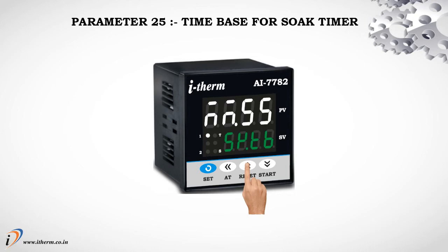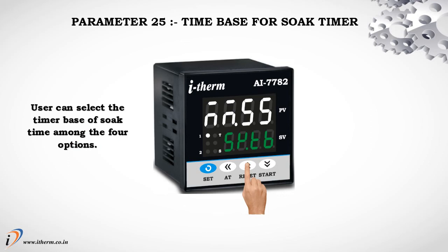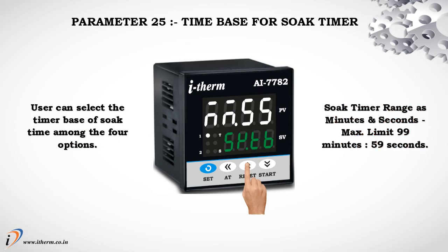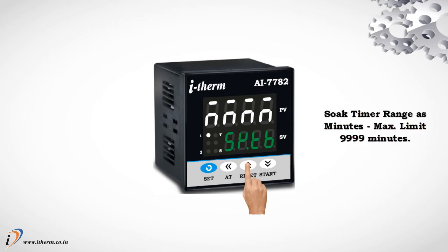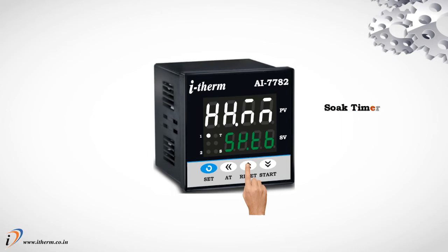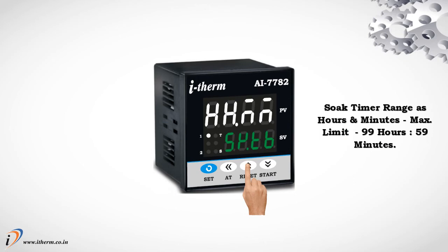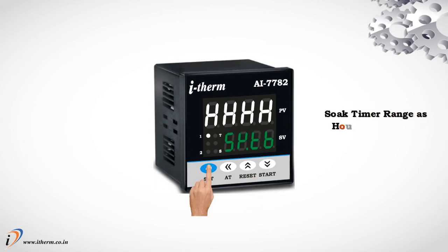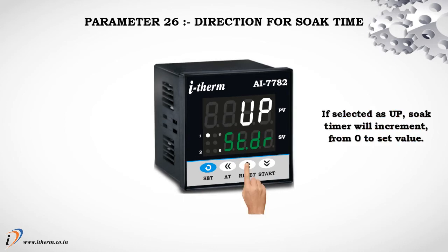Parameter 25, time base for soak timer. User can select the timer base of soak time among the 4 options. Soak timer range as minutes and seconds, maximum limit 99 minutes, 59 seconds. Soak timer range as minutes, maximum limit 9999 minutes. Soak timer range as hours and minutes, maximum limit 99 hours, 59 minutes. Soak timer range as hours, maximum limit 9999 hours.